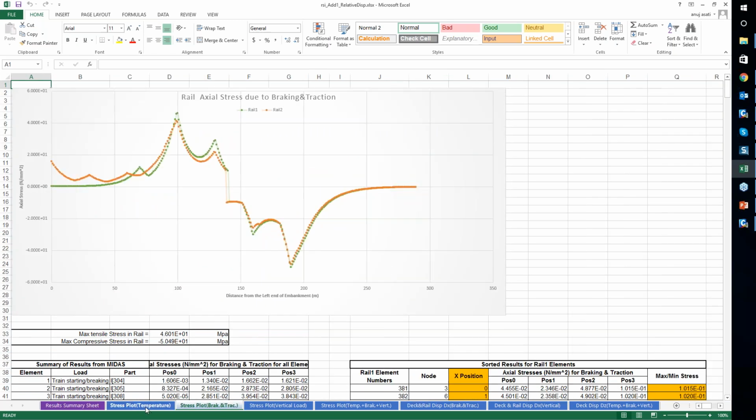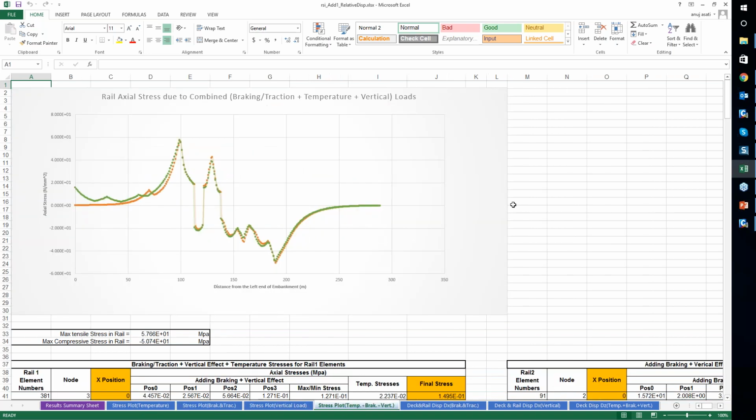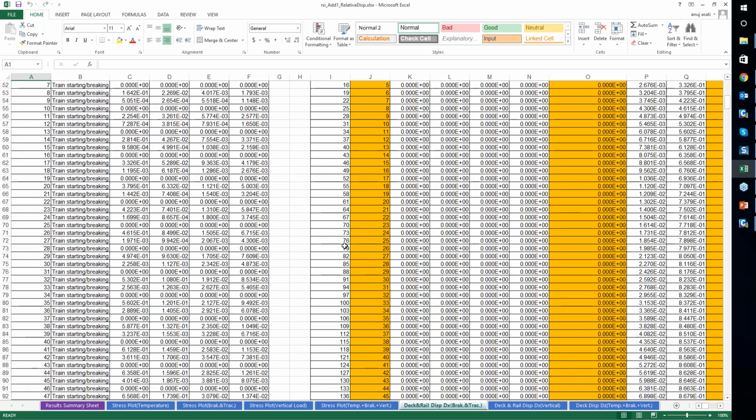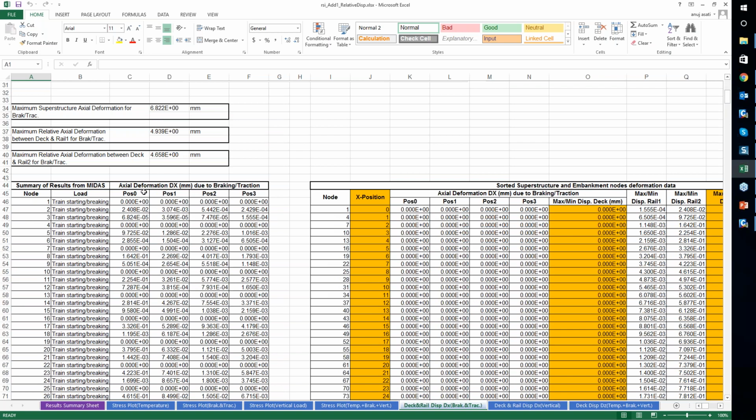The rest of the sheets are individual stress extractions. This will be automatically generated for simplified separate analysis by the software. It is a very tedious task to extract results from all the models, compile them and get an envelope. That part has been made easy by the software, and this type of summary report is generated for you. You can see the stresses for each and every moving load, with 4 load cases for each case.